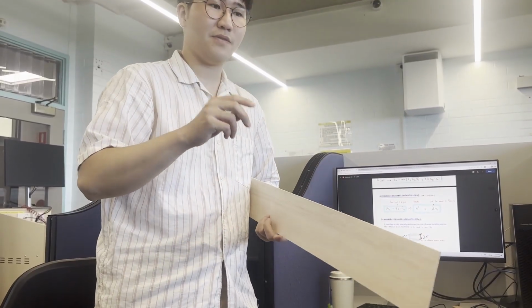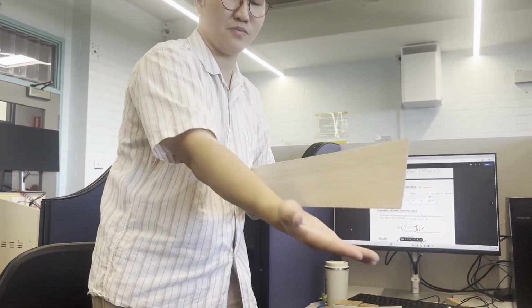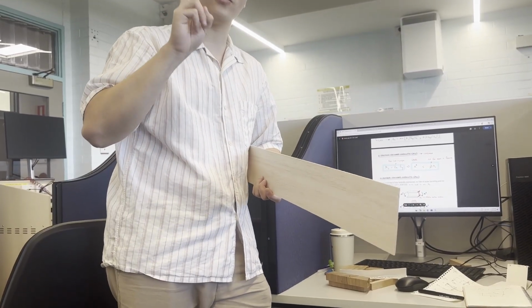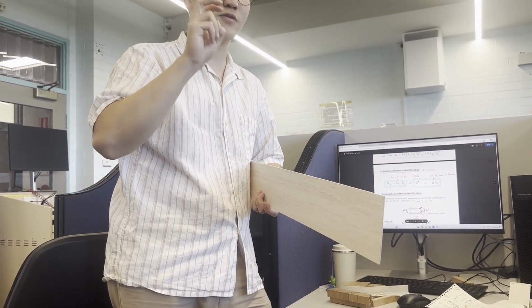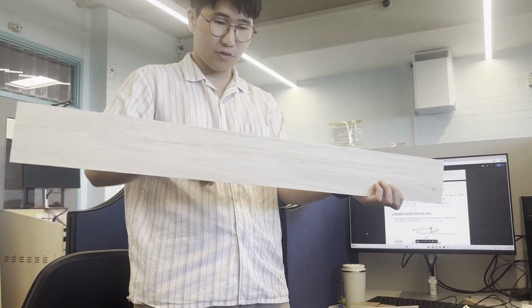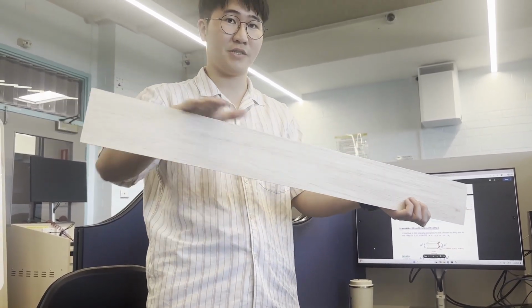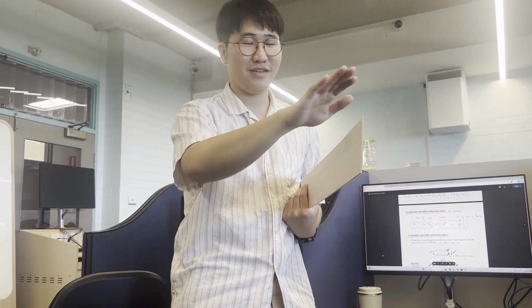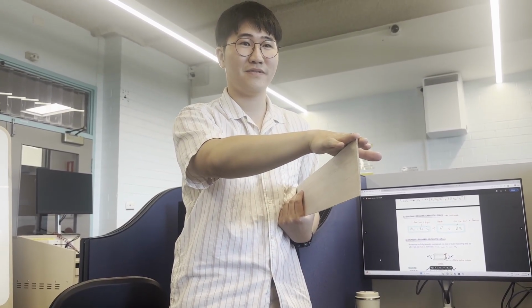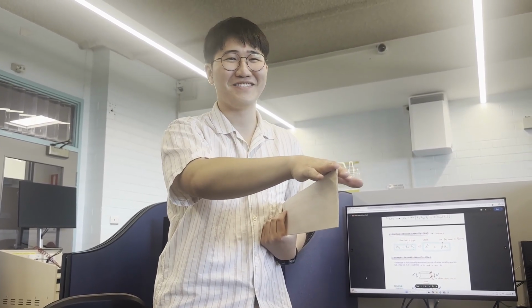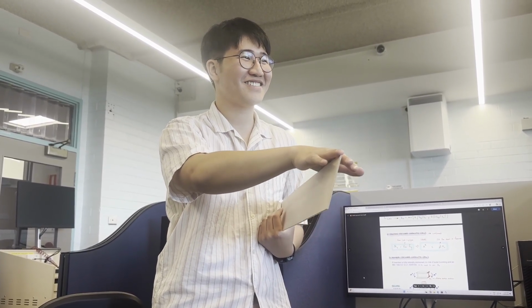So imagine it's an I-beam, where we have a top flange and bottom flange. What we say is that there's a critical flange, okay? The critical flange is the one that's going to buckle out. So for a simply supported case, the critical flange is your compression flange, okay? For a cantilever, it's a tension flange, okay? Make sense? It doesn't make sense to me, but it is cool, right? It is interesting.